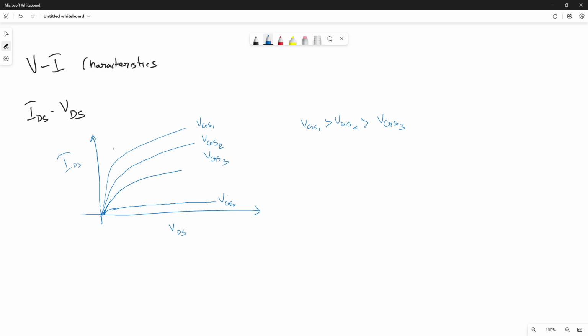No, that is with respect to VGS. What I'm asking is, as I'm increasing VDS, saturation is occurring. Here VGS is all kept constant. So why is it saturating with respect to VDS? Again, we are just trying to intuitively understand it. We are not setting up any explicit relationship.